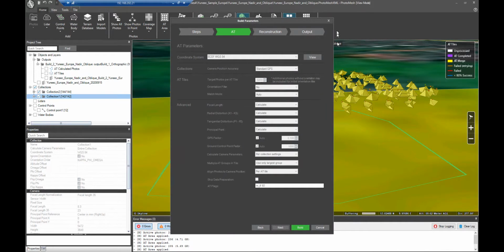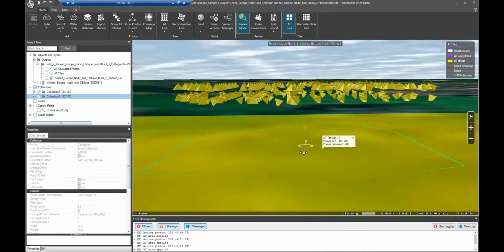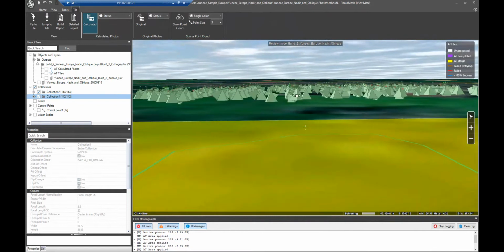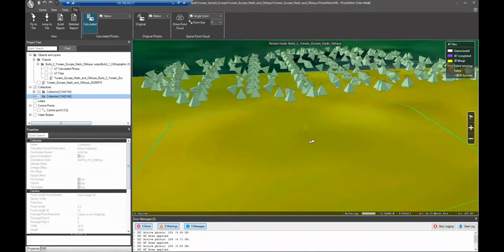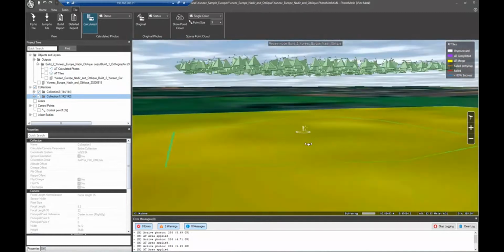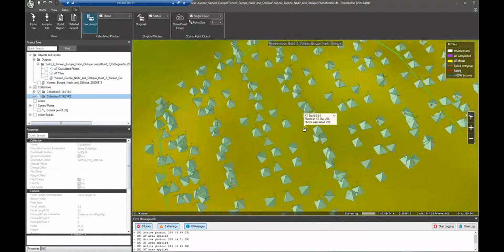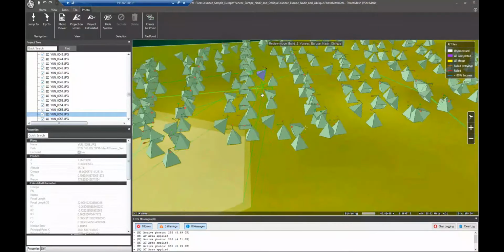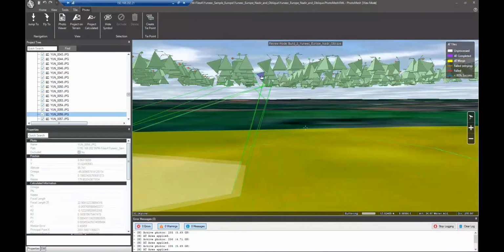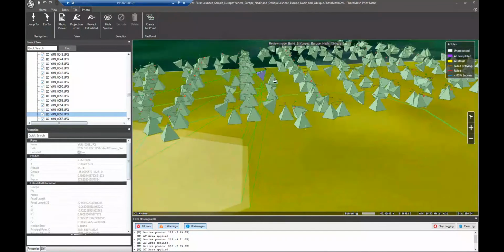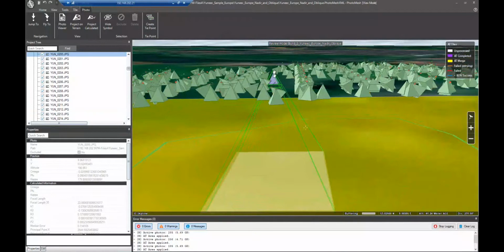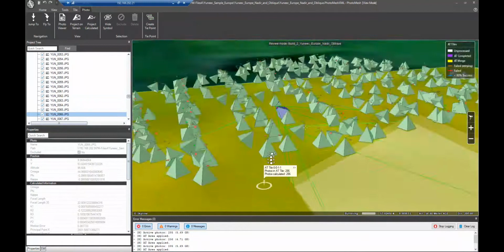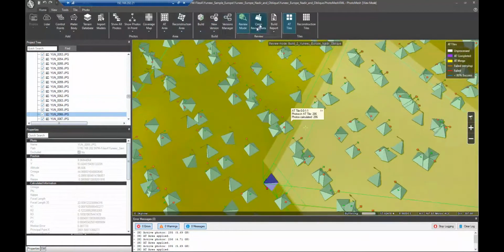A standard GPS does give more freedom level, and we can see that after the calculation of the images, they line up because they were flown at the same altitude. It's just the GPS accuracy had some variation between the two flights. So once the calculation happens, you see the nadirs, the obliques. You can see the original location of the image and then the final location of the image. So it moved it into the right position. The nadirs shifted a little down, and the obliques shifted a little up. But at the end of the day, they're all correlated pretty well to one another.